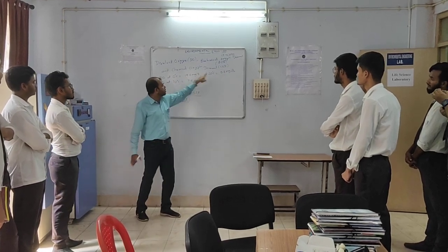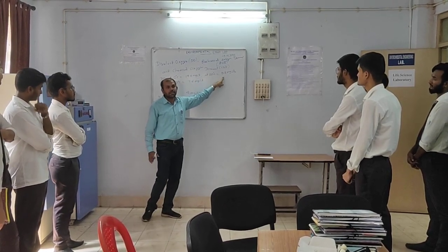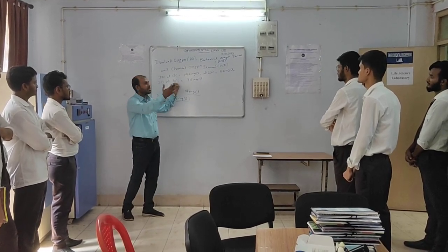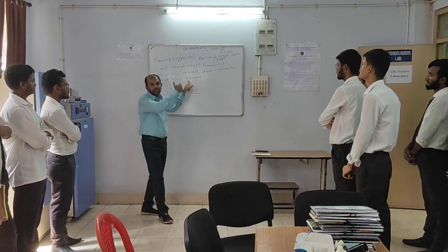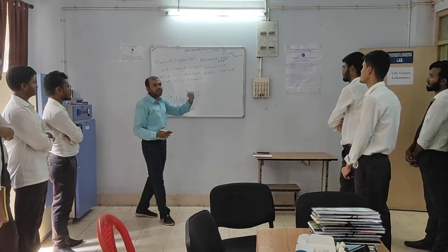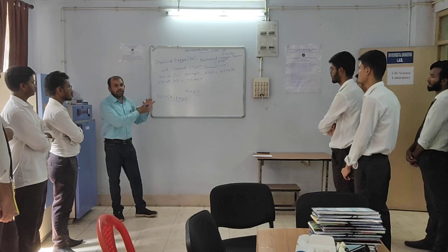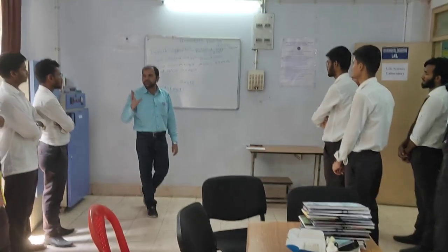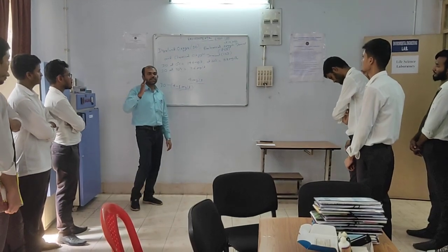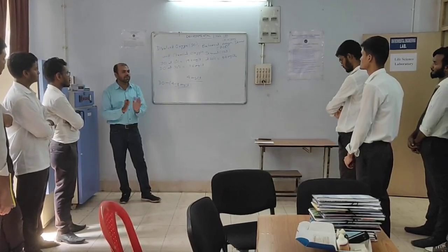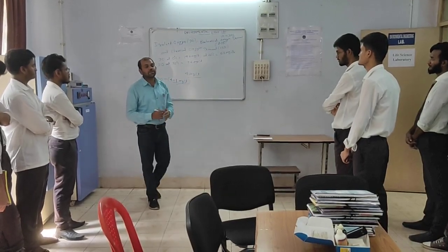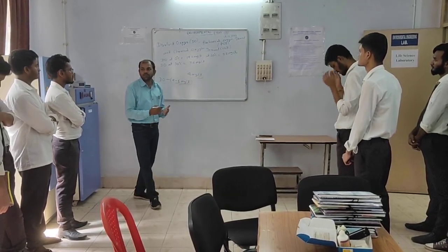From 14 it is reduced to 9.2, and when the temperature is 30 degrees centigrade, the dissolved oxygen level reduces to 7.6. So the higher the temperature, the lower the rate of dissolving of oxygen. That is why in wastewater, which has an average temperature 10 degrees more than normal drinking water, the dissolved oxygen level is very low, and also that oxygen is